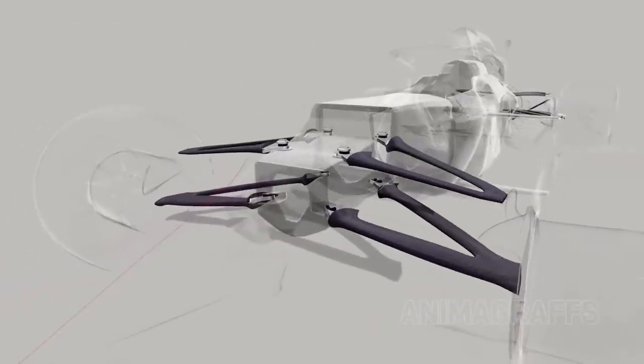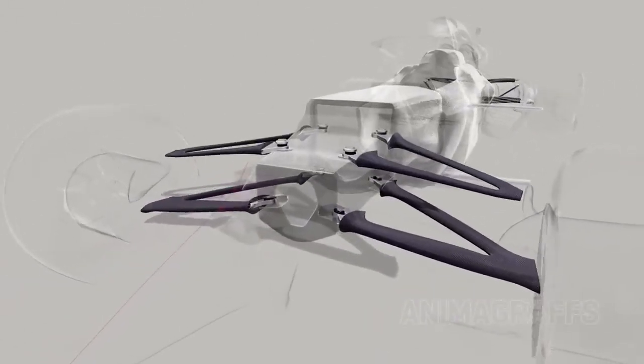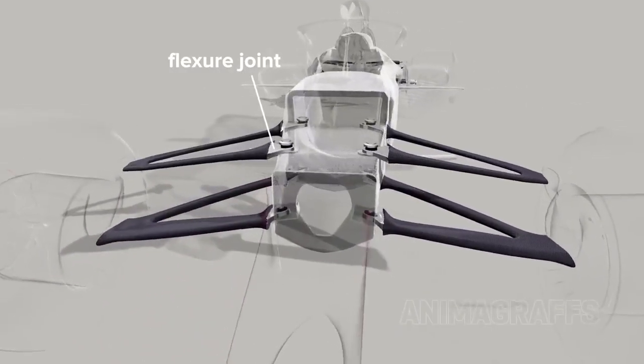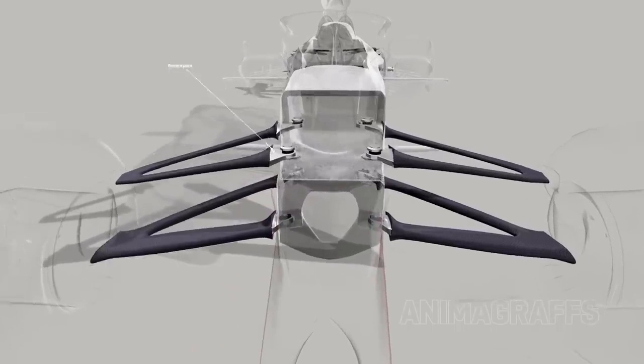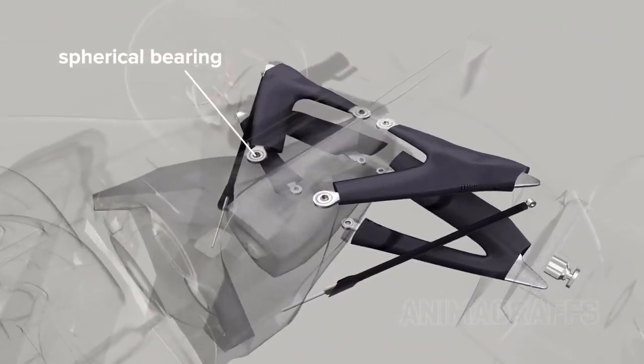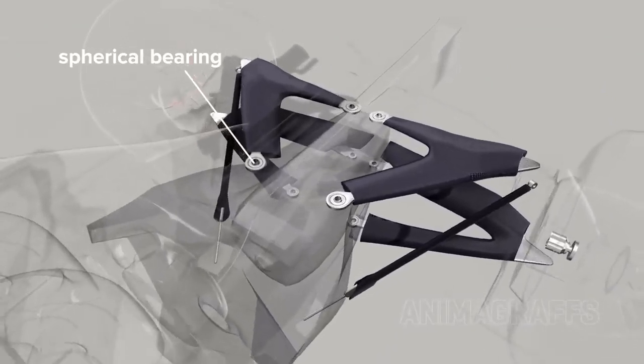At the front, where heat isn't an issue, wishbones are directly attached to the monocoque and have simple flexure joints designed to bend under load. At the rear, where engine heat can be intense, spherical bearings are used.